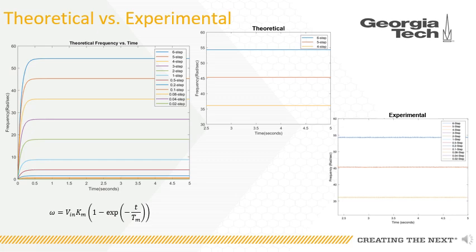The fluctuations are not large, and they are centered around the nominal steady-state frequency, but they are present for all voltages over the entire domain of time. Several assumptions were made in the derivation of the model. Friction was assumed to be negligible, and motor inductance was ignored. The effects of these on model parameters, and perhaps others, lead to steady-state frequencies that are not perfectly constant.